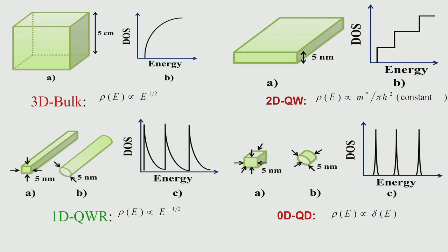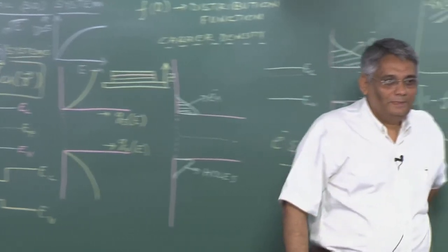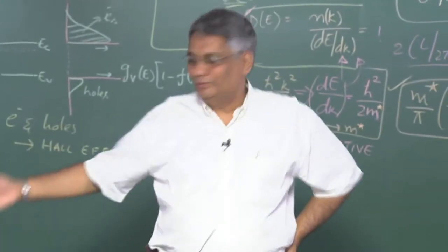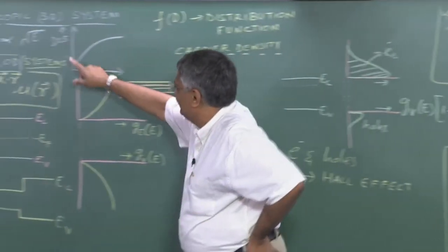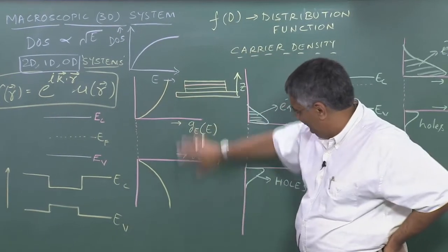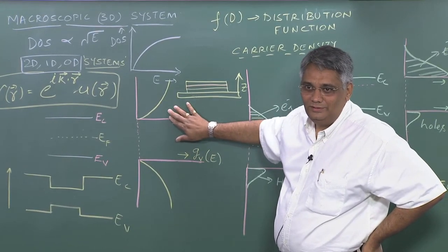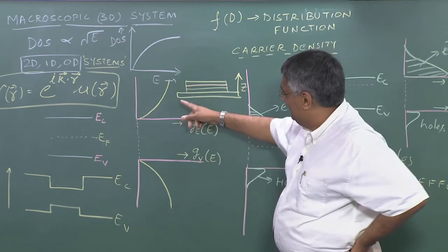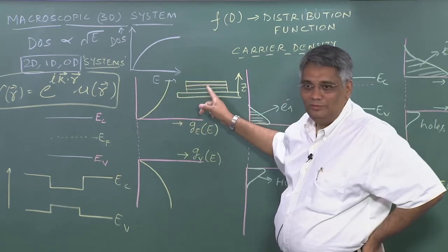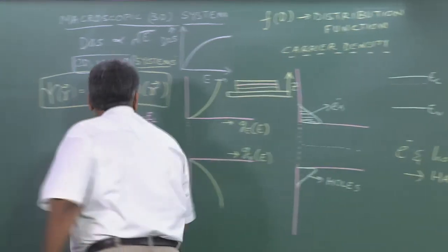Now, I plot all this for a semiconductor. It's easy to do it, we understand this. Density of states versus energy varies like this for a bulk system. So, you also know the reason why this plot is plotted this way in the case of semiconductors. And now if you have a two-dimensional quantum well of the same semiconducting material, what happens to this?